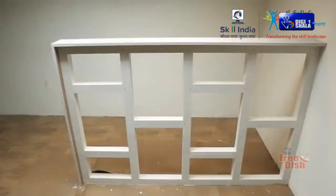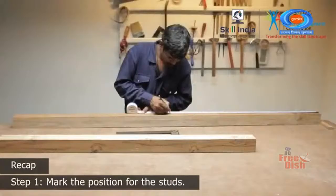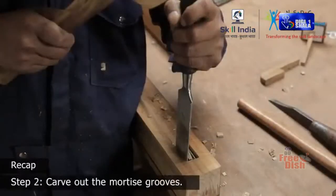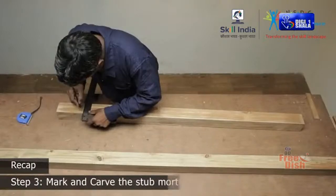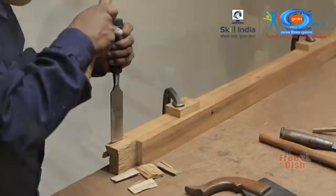Let's quickly look at the procedure once again. Step 1. Mark the position for the studs. Step 2. Carve out the mortise grooves. Step 3. Mark and carve the stub mortise grooves. Step 4. Mark and cut the tenons to size.